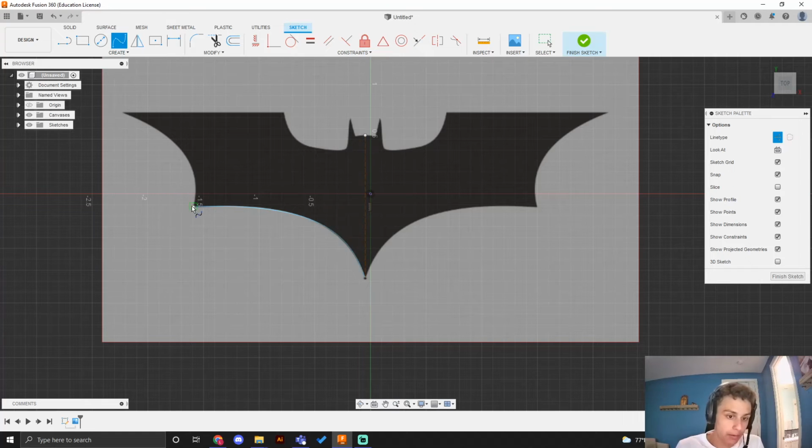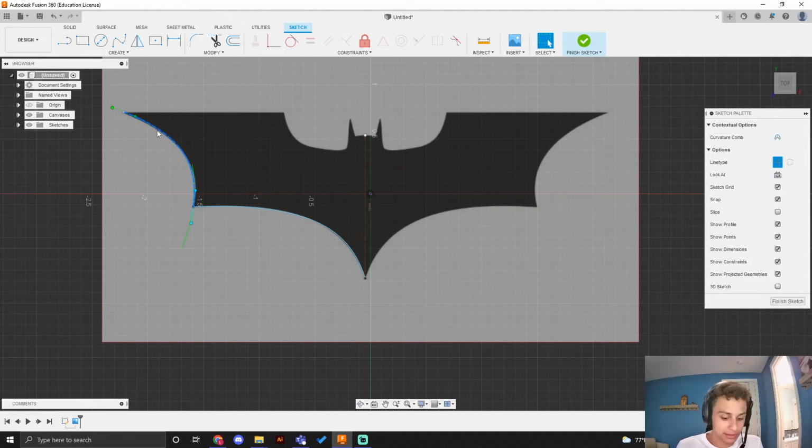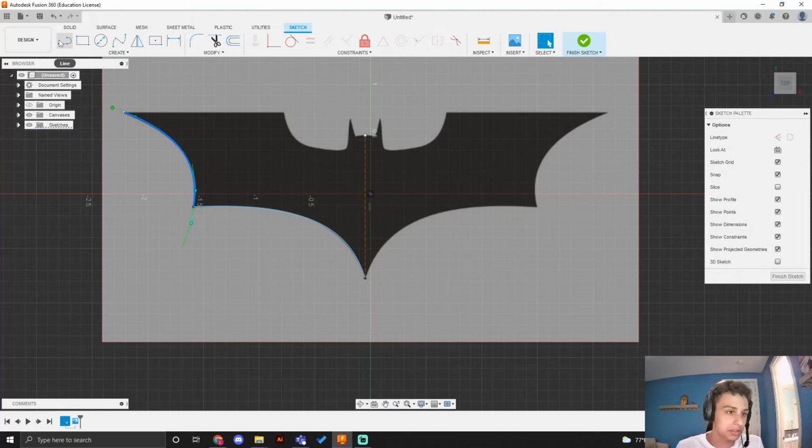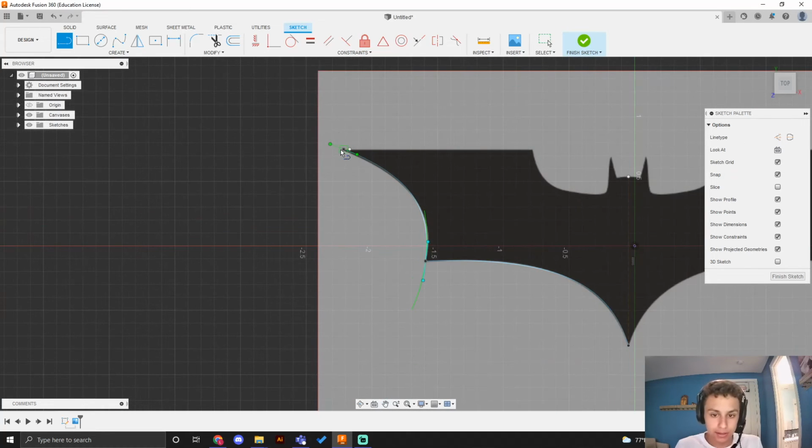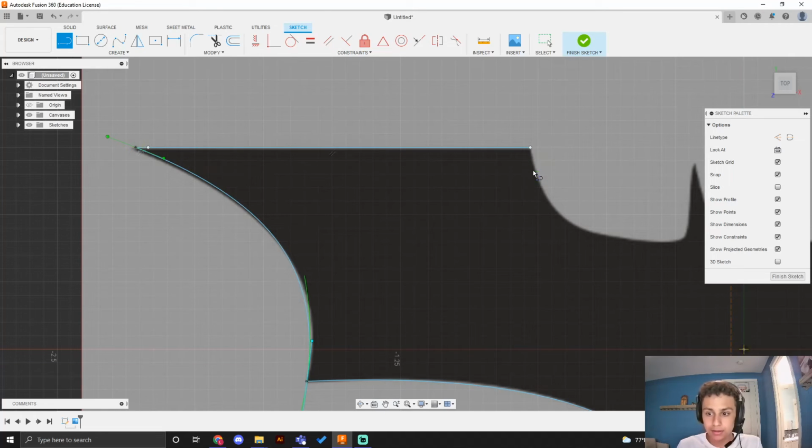I'm gonna do the same thing right here, here to here. You can tell I'm just estimating here. When you're actually making a sketch that needs measurements, obviously, you can use your sketch dimension tool, but for this case, I'm just showing you how to trace it. Same thing, don't make construction. Forgot to change that. Then we're gonna go over from to line. Why is it still in construction? It's pretty annoying. Let me click out of it. Okay, and I'm gonna click over here about.